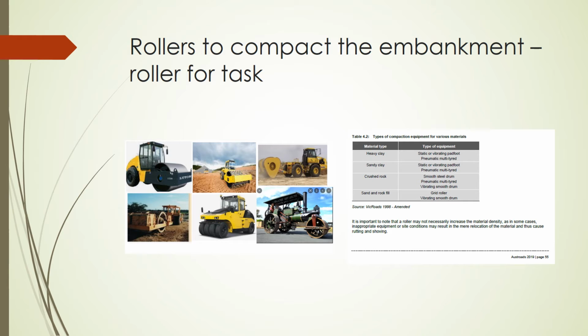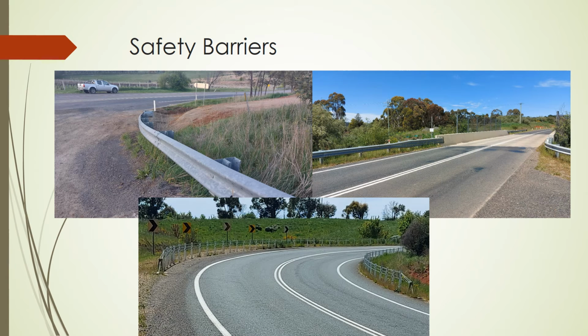The embankment fill will require a grid or compacting roller because we're expecting to see those larger folds. And we'll also need pneumatic tyred rollers for the base construction. An important point with these rollers is the homogeneity of the fill. There's a huge problem with large rocks in the fill, especially on the smooth drum rollers. It will basically take all that point loading that the rollers give and put it into one little section. You get a weak spot in your road. So those sections must.